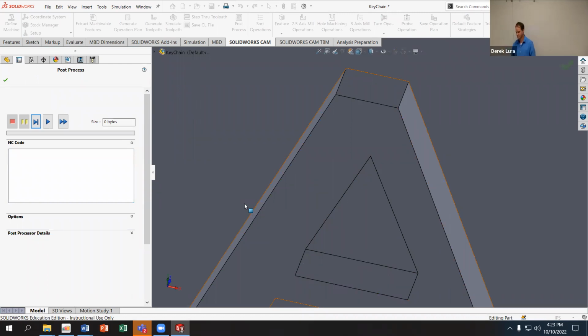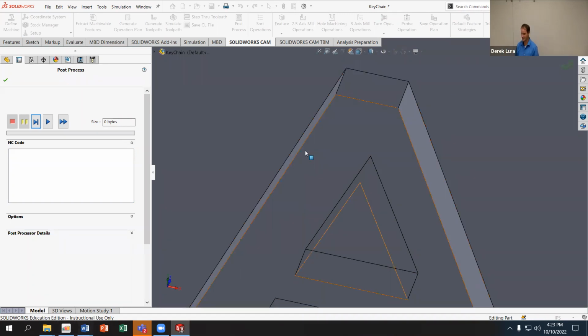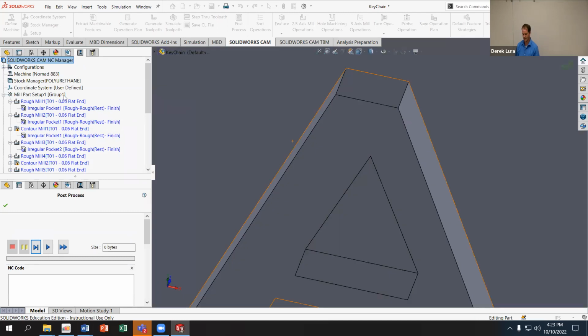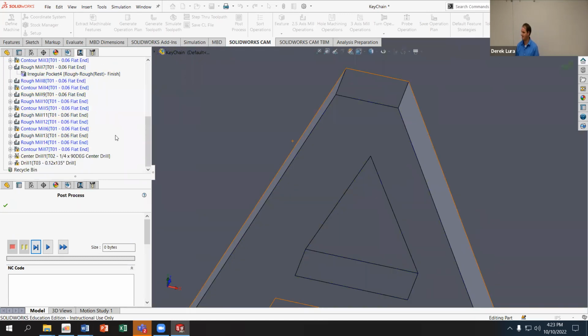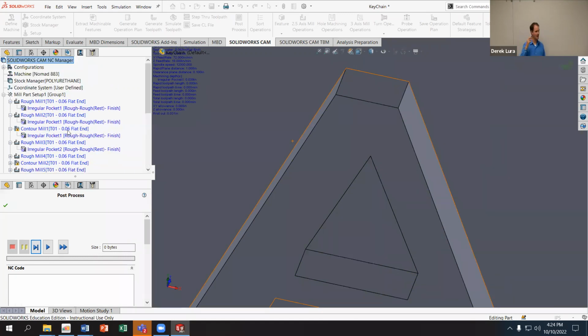That's fine. Those are the ones that are going to cut. Yeah, anything that's in blue on here, let me go back to our operational plan. All these ones in blue are not being performed, right? And also the ones with the exclamation marks, those could be performed, right? They have a tool path, but I don't have the right bit for them. So the ones in black that don't have an exclamation mark are the ones that would actually get generated with this current plan, right?